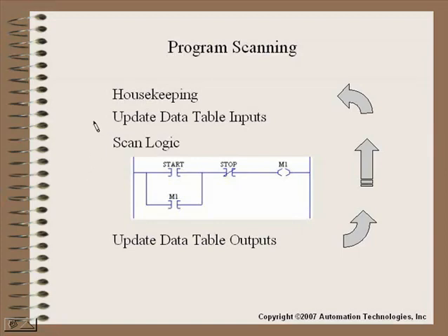What you need to understand first and foremost about a PLC program is it does not just operate from the top and go to the bottom and stop. That would not work well at all. I mean, it would scan through one time and then you would have no further operations.